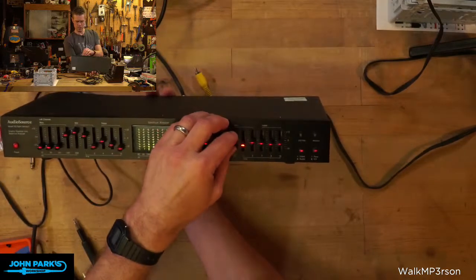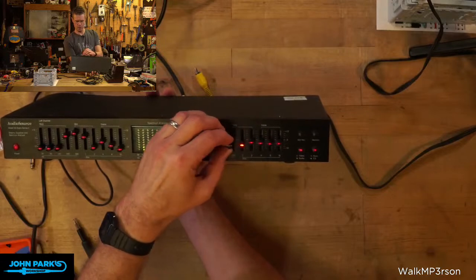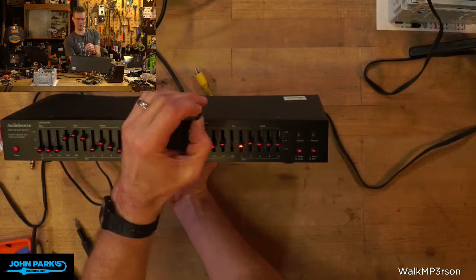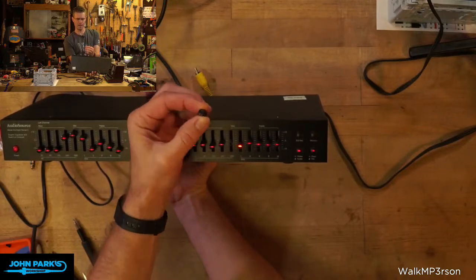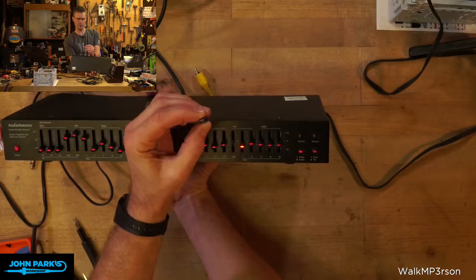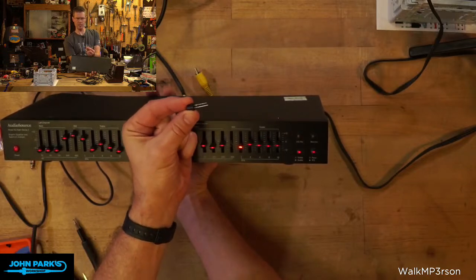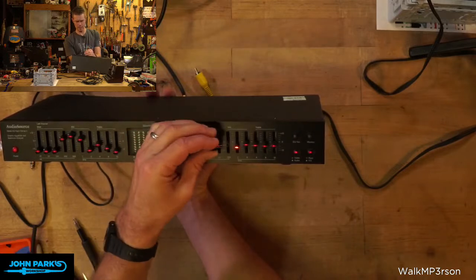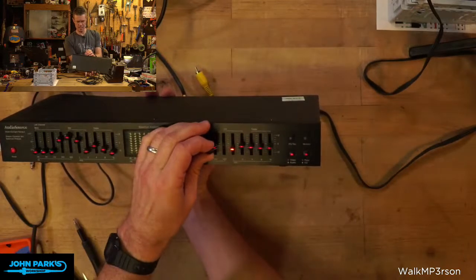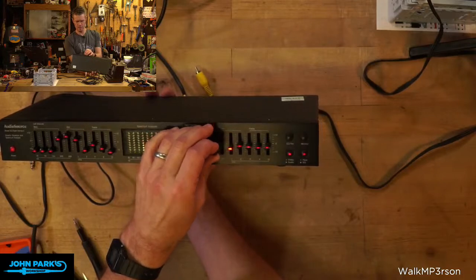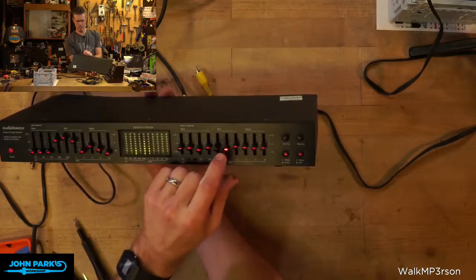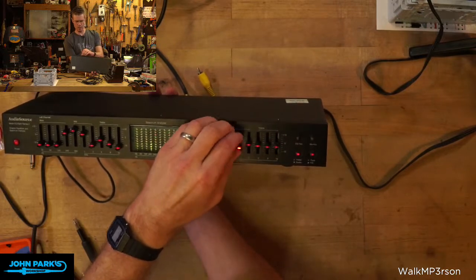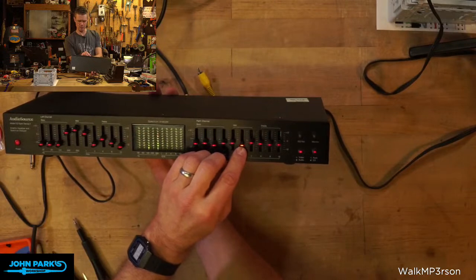The reason this was fixable is that the knobs are LEDs. They have a little plastic cover and a little light pipe, a little lens, and then it's literally a straight up 5mm LED, or maybe a 3mm LED, with contacts inside of the fader slider handle. So since it was missing one, I'll leave that one in there. I've got it jammed in there and heat shrink to it.